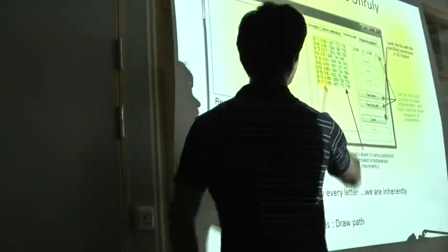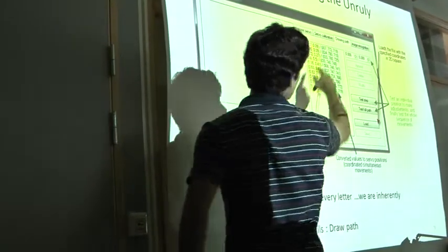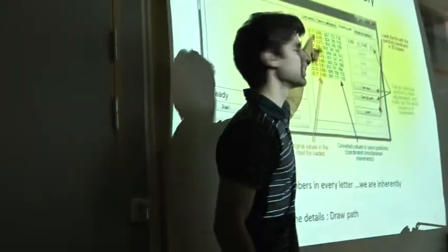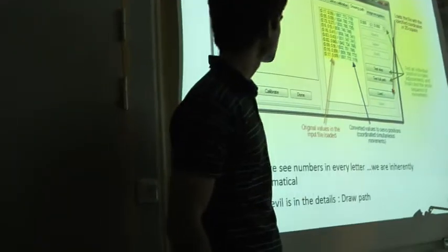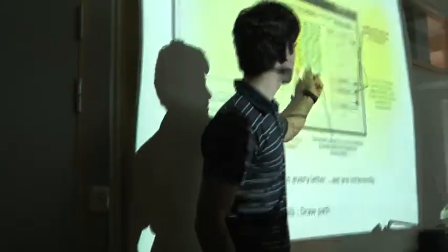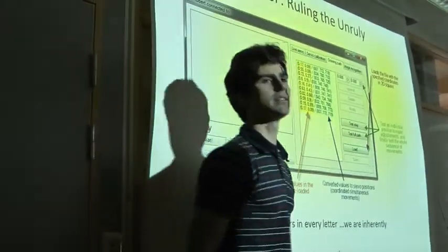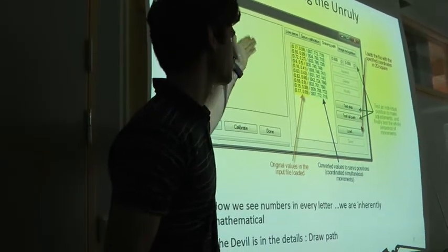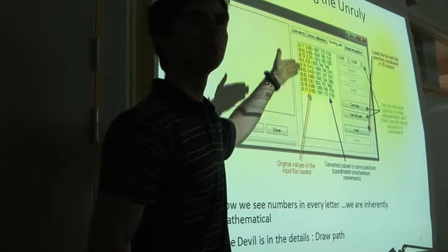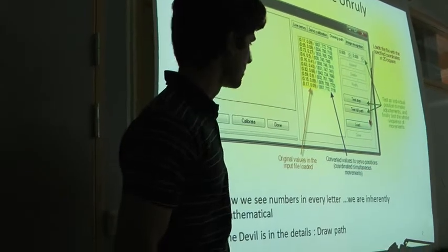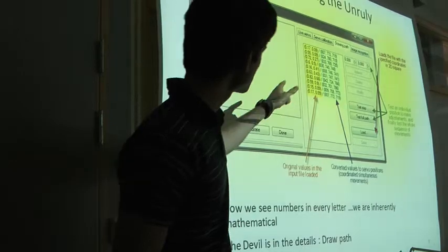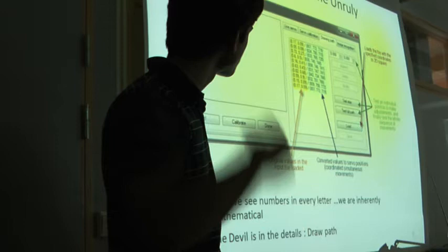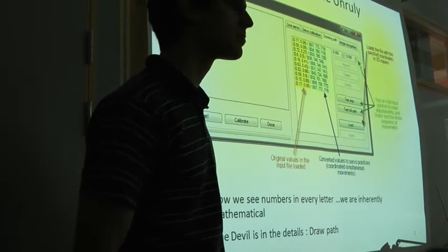Okay. Here we can see, for example, how we can specify this in a file. The coordinates in 2D, which are proportional in these 2 dimensions, the steps to draw the letter, and how they are converted to the 3D space, the position of the motors of the Hubert, basically the base, the shoulder, and the elbow. And I think that is an A, right? Yes, this is for the A. So basically, we recorded the various positions for A into the system.